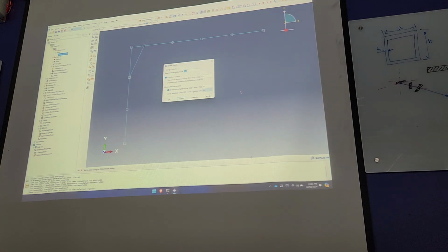Yeah, you can't have an element size that is only 30, yeah? That's not a beam. Remember those stiffness matrices for springs that we did? There's a similar thing for beams. They are most accurate if we have a ratio of roughly 1 to 7 or 1 to 10, cross-sectional area to the length.